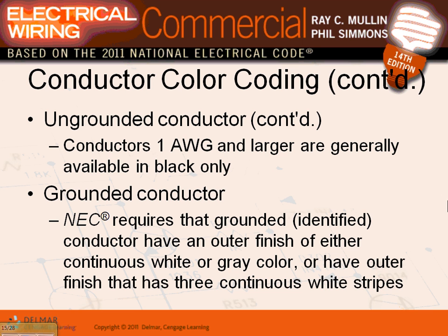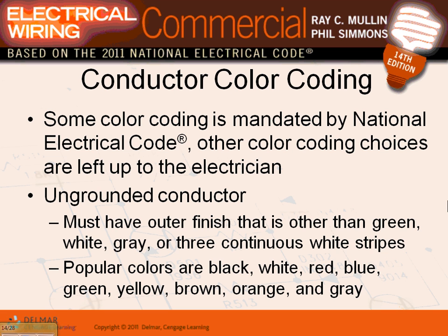On that yellow, brown, orange, are those considered ABC as standard convention? Yellow, brown, orange, yes, ABC. And in that one, black, red, blue. Black, red, blue is phase A, phase B, phase C, absolutely. And the white, of course, the neutral. And that equates to XYZ. XYZ, thank you. XYZ on the receptacle, yep, absolutely. When we land them on the receptacle, it'll be XYZ, phase A, phase B, phase C.